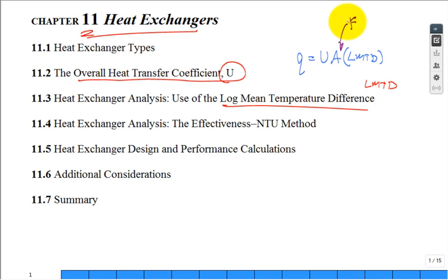But basically, the correction factor F is gone. You can look at previous editions of this textbook, and they had it in there. But that's gone. And now, if you really want to do something more than concentric tube, you use the effectiveness NTU method. A little more abstract, but very, very easy to use, very powerful, and they have it for all different types of heat exchangers. And this book just is limited. It just has a few pages devoted to heat exchangers. Other books, the whole book is on heat exchanger analysis and all kinds of crazy configurations.